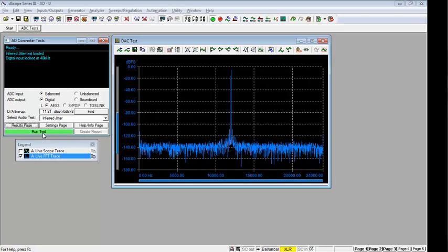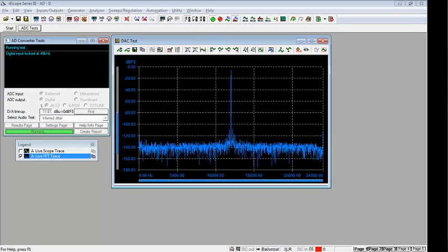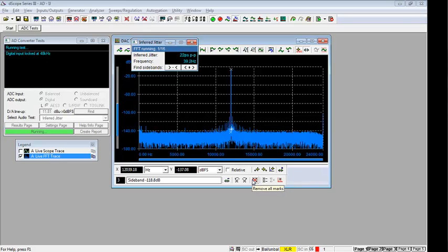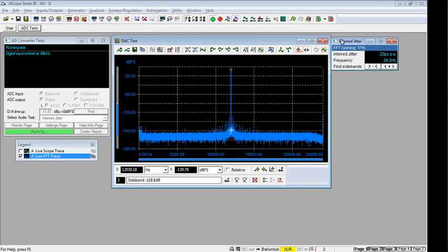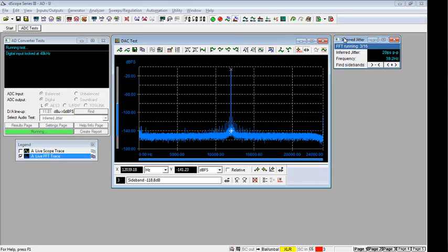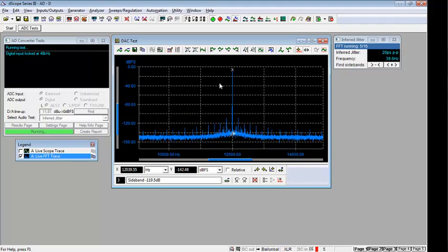So if that's the case, then I can run this test, and what this will do is first of all engage a large FFT size and also some averaging. And I've also got this dialog that has now popped up over here, and let's say I zoom in a little bit on the tone component here at 12 kilohertz.